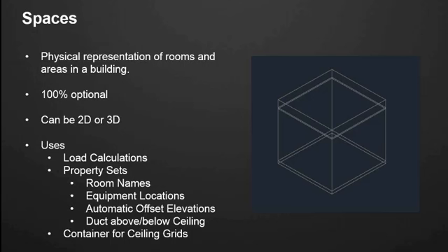So if you go to place an elevation tag and the duct is below the ceiling elevation, instead of reporting the elevation, we can set up the property sets so that it reports that it is below the ceiling, or any elevation that you represent to be the ceiling. Say you have a ceiling elevation of 9 feet and you want everything to be above 6 inches above that ceiling. Well, then you can represent the minimum elevation to be the ceiling elevation plus that 6 inches. And anything that goes into that no-fly zone, so to speak, you could then call out in a tag. So as soon as you tag your duct, instead of calling out the elevation, it could call out that it's below the ceiling.